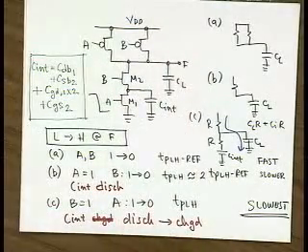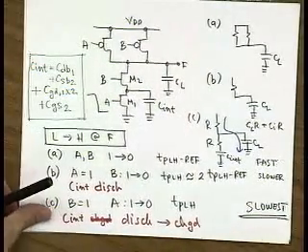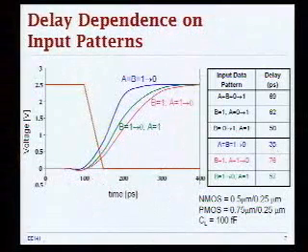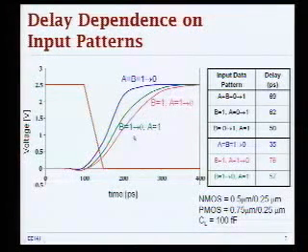Okay, thank you. All right, let's go quickly back to slides. This shows you the 3 different cases. When you have 1 to 0, propagation delay is 35 picoseconds. When you have only one PMOS pulling up the C load, with nothing going on with the C intrinsic, you have a little bit longer delay, 57. And finally, when you're charging both of these, in the worst case, you have this delay of 76. So you see you have a 2x difference in propagation delay.